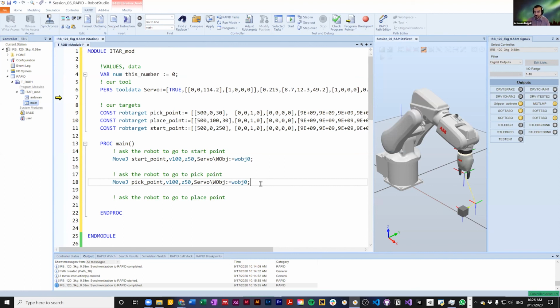In order to get to the full speed of the robot, which is different for each robot that we have, you need to physically bring a switch, like a key, and unlock that power, and then make sure that everybody has left the room and all the safety systems are on. Then we can run the robot at speeds of, for example, 1000 for the big robots. But for this small one, I think we cannot go beyond 500 or something like that. So if the speed is too much, it's basically going to be capped automatically.